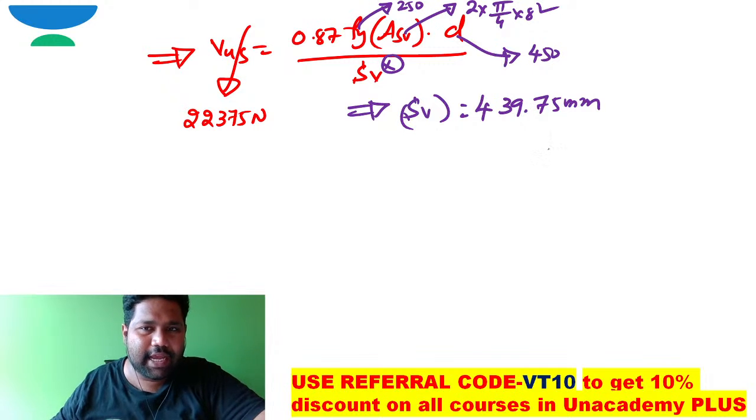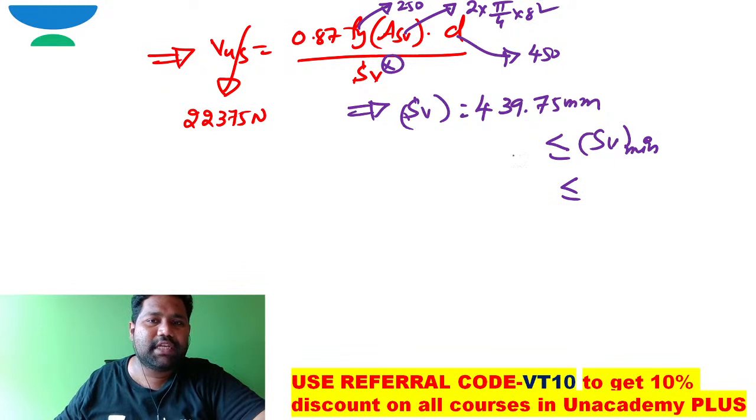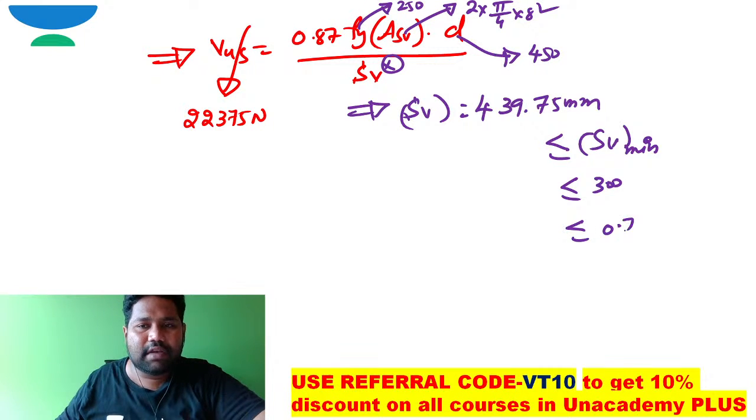Directly you should check like this: Sv should be less than the maximum shear reinforcement spacing. Sv, the spacing of this shear reinforcement, should be less than or equal to 300. Spacing of this vertical stirrup reinforcement should be less than 0.75 times d, which is how much you got? It is 337.5 millimeter.